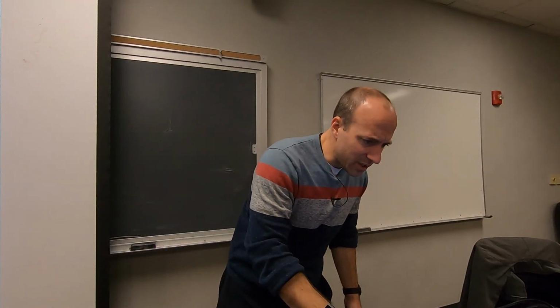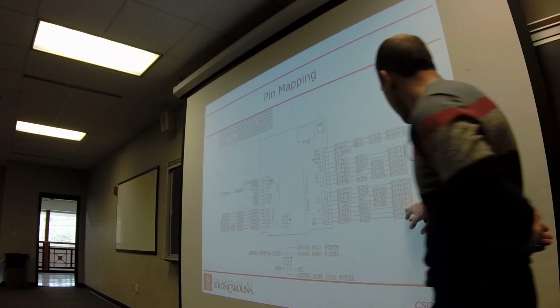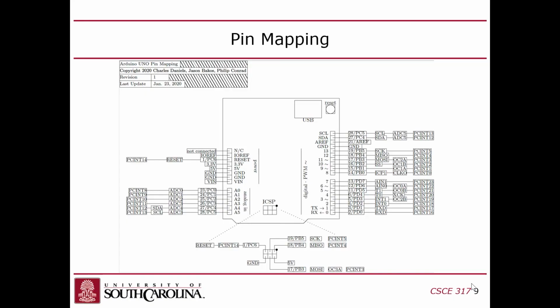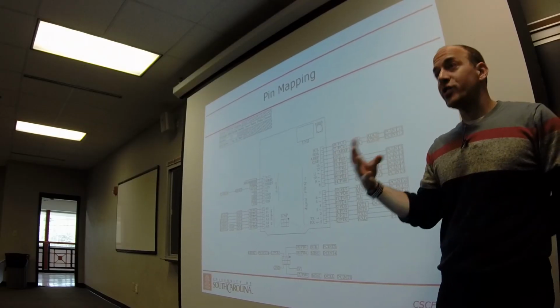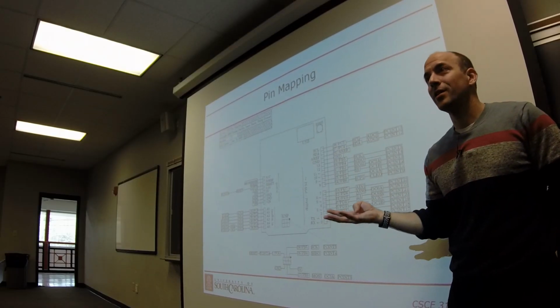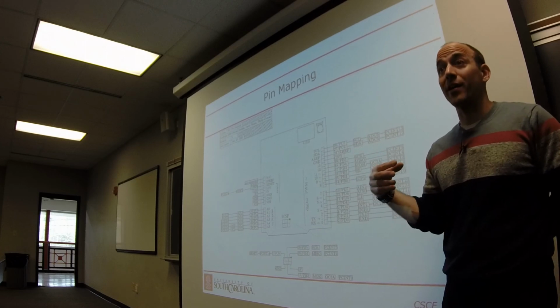The other issue with that, by the way, was, yes, here was the problem. You need 6 bulbs, right? 6 LEDs, and there actually are 6 hardware PWMs because there's 2 per counter and there's 3 counters.